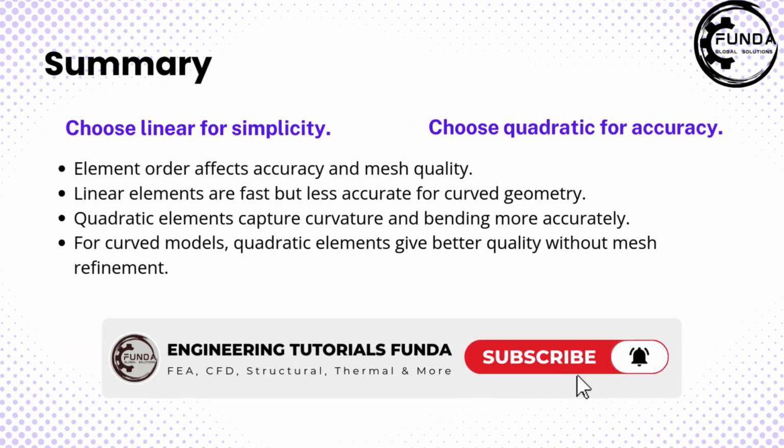To summarize, linear elements are fast and computationally efficient but limited in accuracy, especially for curved geometries. Quadratic elements are more computationally expensive, but they provide much better accuracy for bending, curvature, and stress prediction. A simple rule of thumb is this: if the geometry is straight and simple, linear elements may be sufficient. If the geometry is curved or accuracy matters, quadratic elements are usually the better choice.